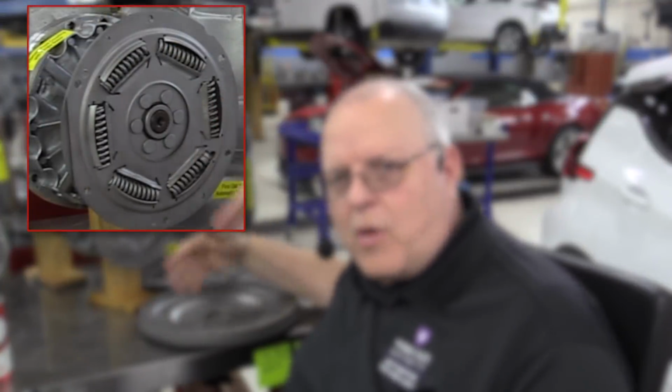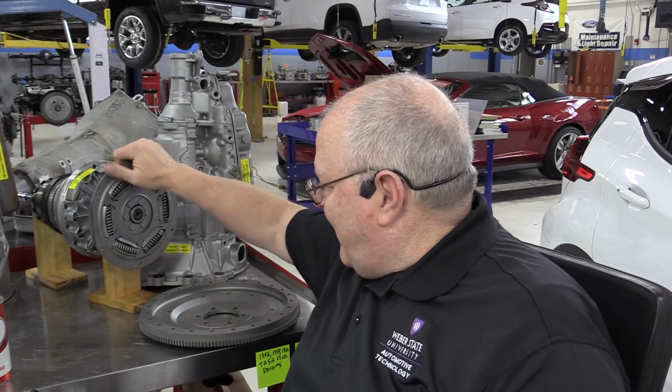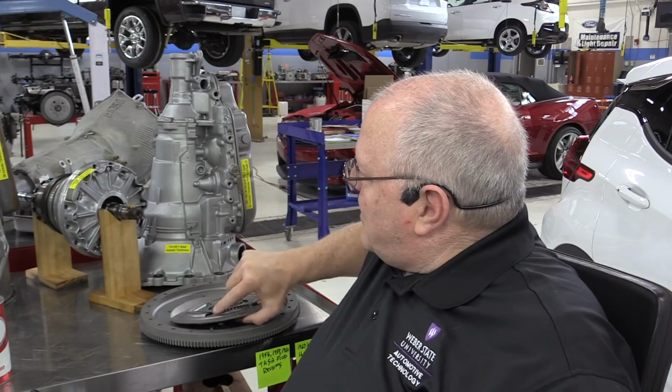There was no torque converter between the input shaft and the back of the engine crankshaft. However, inside of the transmission in this little bulge area right here is this little mini torque converter. And it was a 3-element torque converter with a variable pitch stator, and it was pretty small. And it also would develop a lot of heat and had oxidation and other problems that drove the need for an even better fluid.